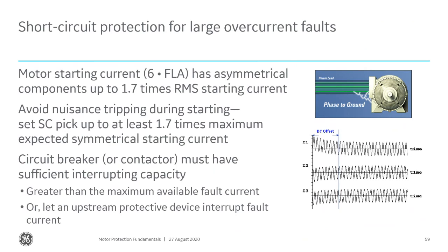The caution here is, if you're using a contactor, contactors typically are fine for starting and stopping your motor, but they don't provide enough interrupting capability. So it's hard for them to interrupt a full fault current. So you may have to trip an upstream breaker for a short circuit fault.